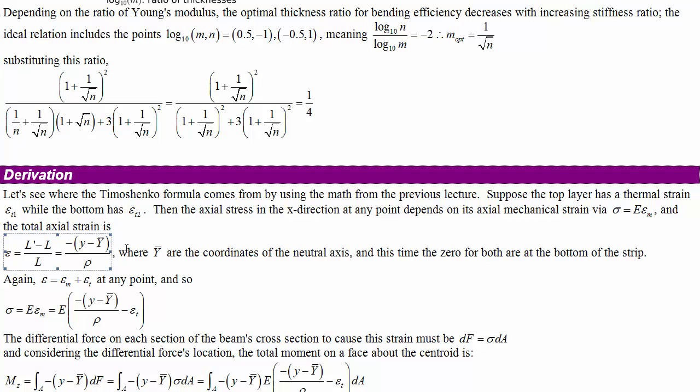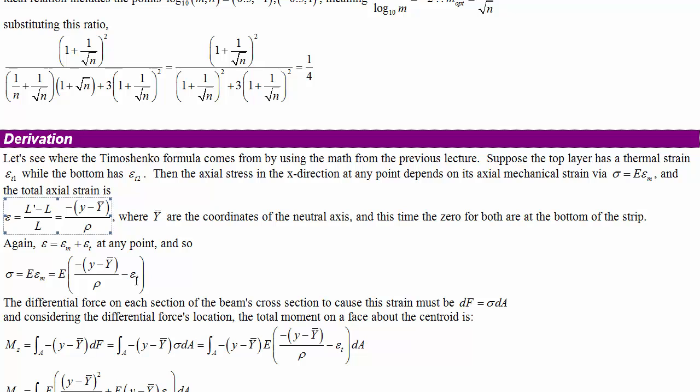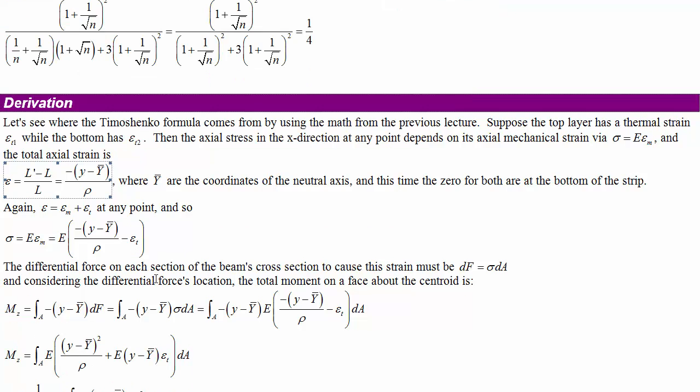Physical strain being the relative length change, now writing it in terms of the neutral axis displacement, so position relative to the neutral axis, divided by the radius of curvature of the bending that results, would be the strain at each point inside the beam. And so the mechanical strain is this minus the thermal strain, or maybe minus the piezoelectric strain if this is a piezoelectric actuator, or maybe minus both if we've got the general case.